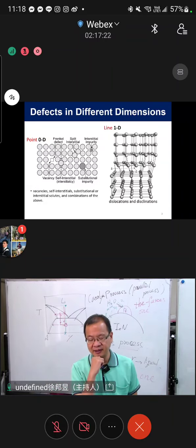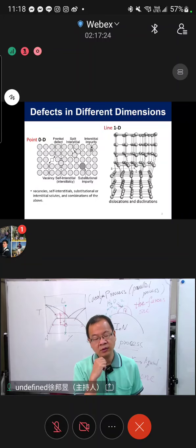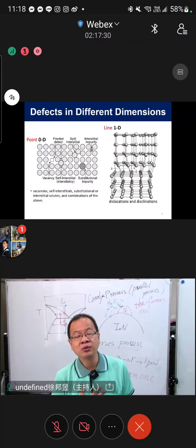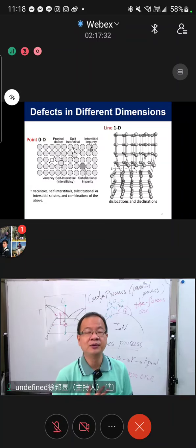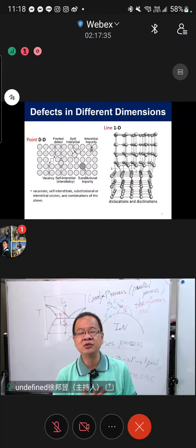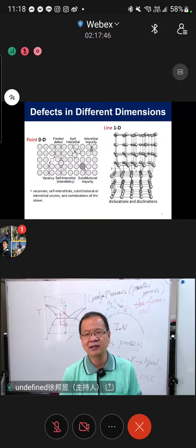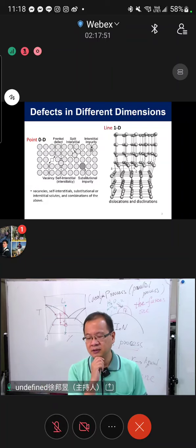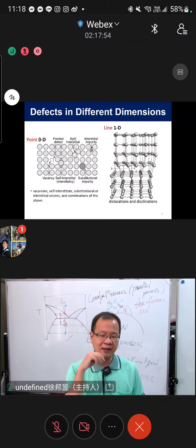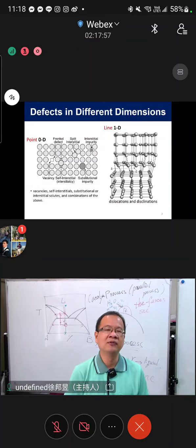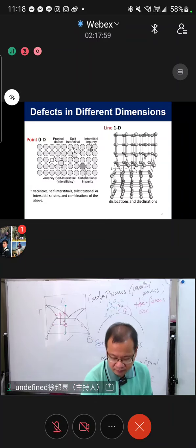And the right one is the very classic dislocation. If it's polymer material, then that's disclination. I will try to cover that, but I cannot guarantee. At least you will learn the most important behavior, the kinetic diffusion behavior driven by zero dimension defects, and that's the most important one for most materials. It doesn't matter whether it is semiconductor, ceramic or metallic. If you have zero dimension defects, that's the driving source of the kinetic diffusion.